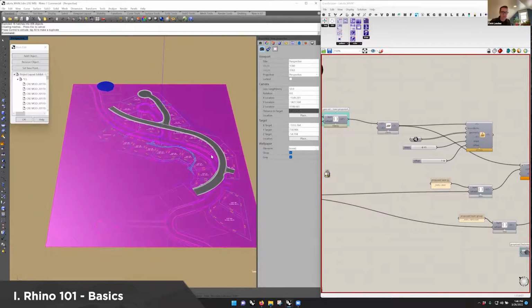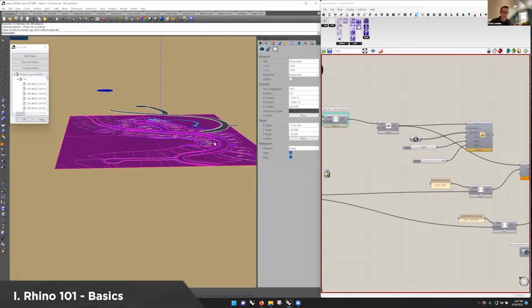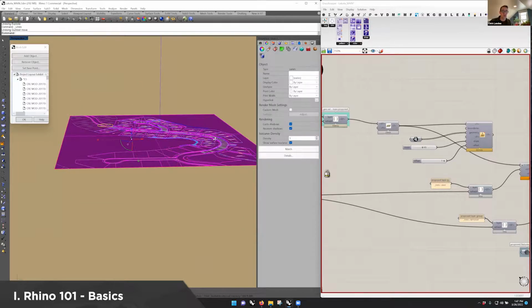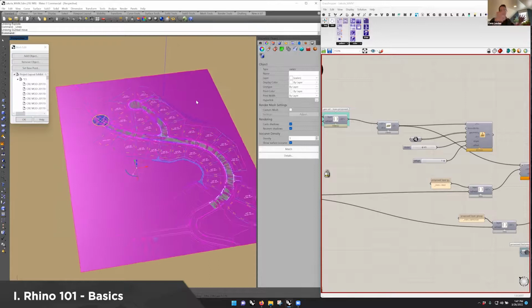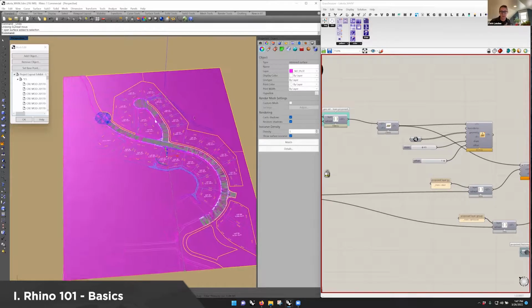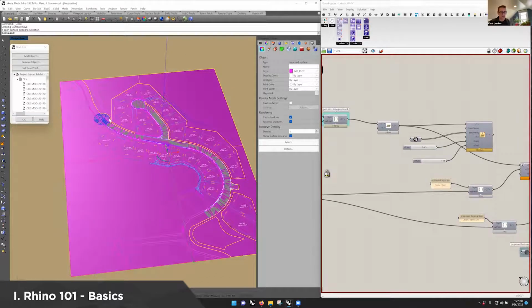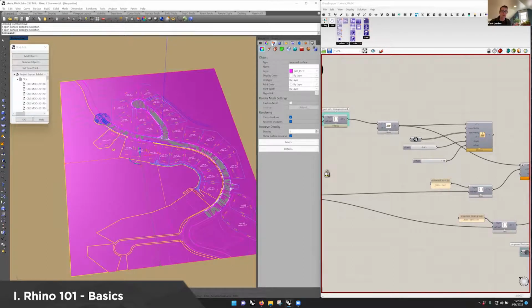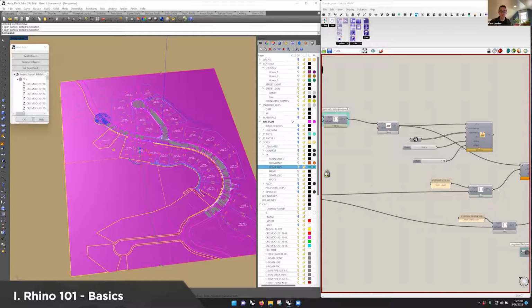But the other thing to know about this is that if you do have all these surfaces sitting on the ground plane, Ben's pulling them up just to show them. If you have them all sitting there on the ground plane, you can use them to trim one another. So if you want to fill in a large area and you just want to trim with the other existing areas that you have, you can do that. So it's a great way of defining your plan, and you can manipulate your plan this way as well. You can easily split a surface and rejoin with another.